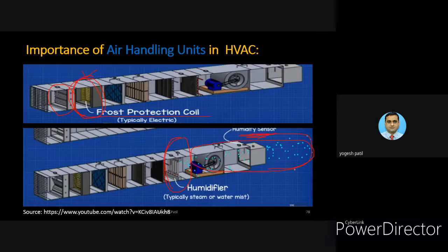There are many more details about this humidifier. The moisture within the air condenses and flows away, and you will find a drain pan under the cooling coil. That drain pan can be used for exhausting the water away from that particular coil. To catch the water and drain it away from the cooling coil, there is a drain pan available with this particular unit.